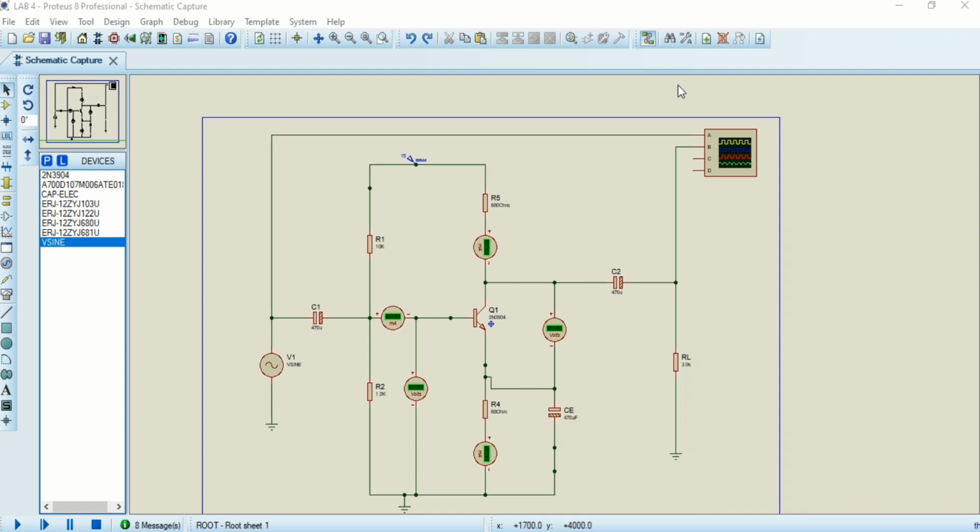I apply a small 30 millivolt peak to peak sinusoidal input at 5 kHz using a signal generator, and connect the oscilloscope to the circuit to observe the input, which is Vs, and the output signal, which is VO. I need to make a sketch of these voltages and calculate the voltage gain AV.